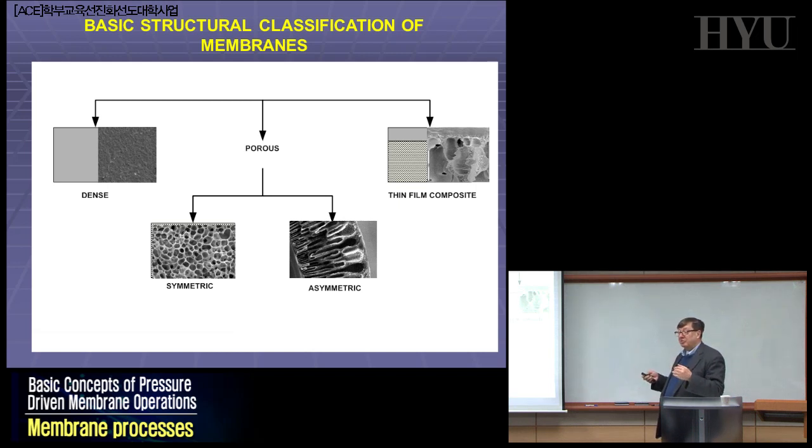This was the invention of Sid Loeb and Sourirajan, who created the opportunity to start with reverse osmosis and to have fluxes across the membranes that were 1 or 2 orders of magnitude higher than before. Because instead of having 200 microns, they had 1 micron. And if you write your equation, the flux was increasing 100, 200, 300 times. And these fluxes were decent for industrial application.